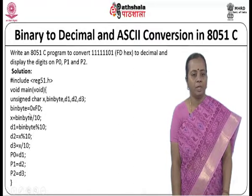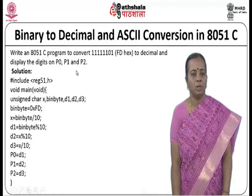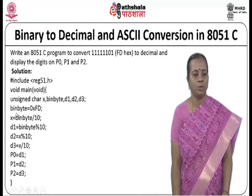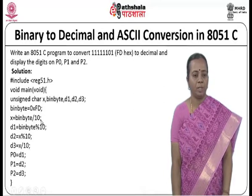So, I will be extracting each and every decimal value that has to be displayed, assigned to port 0, port 1 and P2. So, now we will be looking at 0xFD is given as the input to bin byte, then bin byte is divided by 10.